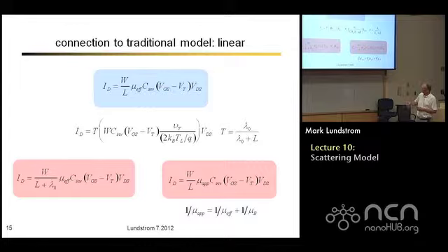And it just says whichever one of those mobilities is smaller will dominate. So if the channel length, and remember the ballistic mobility depends on channel length, gets very short, the ballistic mobility can get very small. It can dominate, and the apparent mobility will be the ballistic mobility, not the mobility that you would get in the bulk semiconductor.